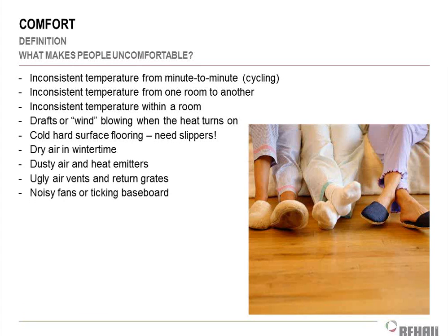And some of these are just pot shots at air systems, so we won't read all those out loud. Sound is actually a good one, right? If it's an air-based system, you're going to probably hear some sound coming out of the diffusers, if not the air handlers themselves. If it's a hydronic-based system and it's radiators and baseboard, you are more likely to hear sound traveling through those pipes than you are to hear pipes traveling through the concrete floor, right? The concrete acts as a sound insulator, and it's not probable that you're going to hear anything on a radiant floor unless the boiler room is on the other side of the wall from your head and you have a loud boiler, right? So a radiant floor is going to be more quiet than any other heating system that you could probably come up with.